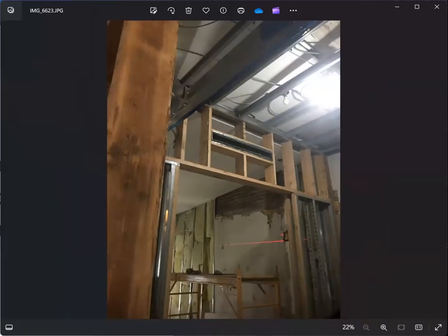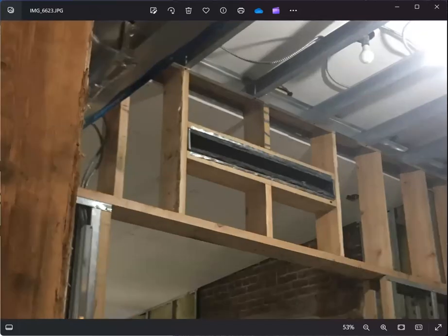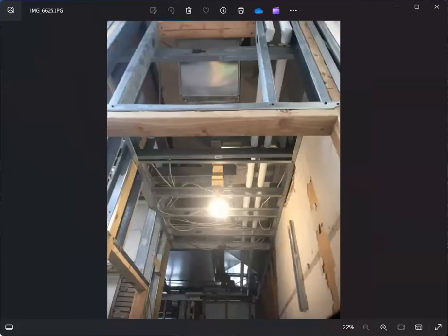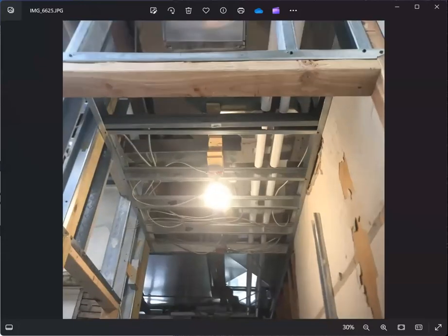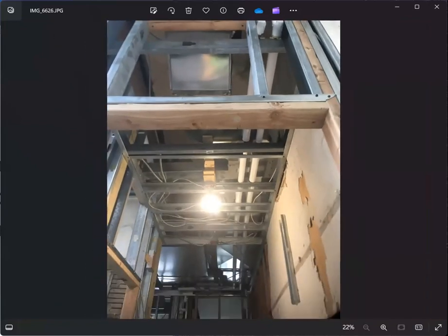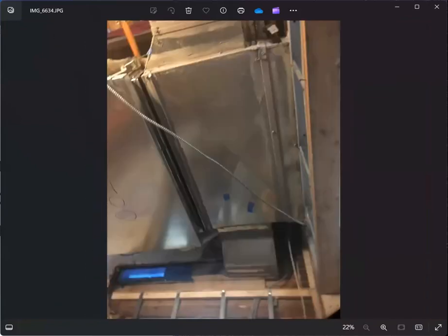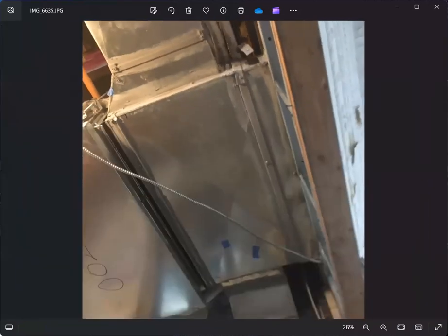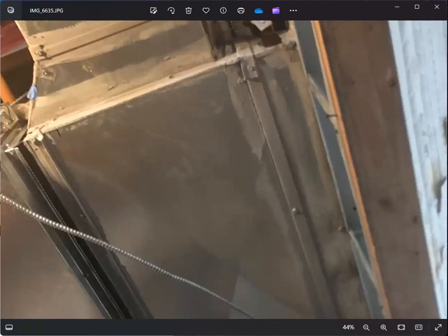Or maybe this is also the purpose for the return air inside the plenum. The plenum is your ceiling. And the ductwork piping. Make sure every joint of the duct is sealed up to prevent air leakages.